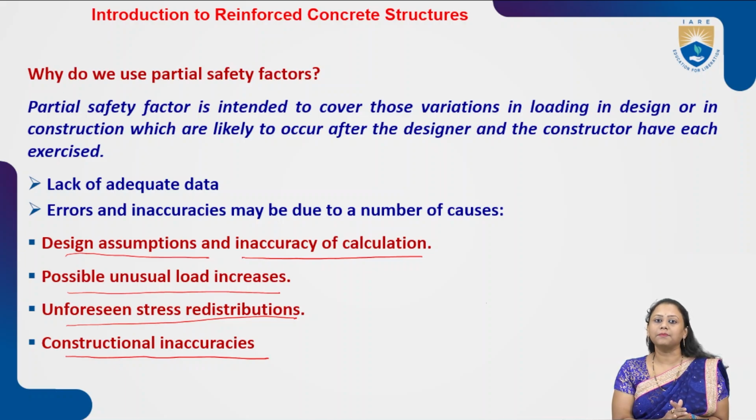To reduce the gap between the real structure and the construction practices, the construction procedures, and the assumptions used in the calculations, to meet the gap between all these inaccuracies, we are going to use a partial factor of safety.